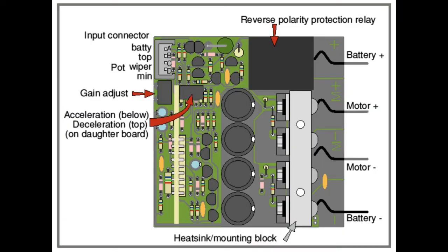We now come to the power amplifiers that drive the motors. When discussing voltage control, we assumed a smooth DC voltage. If we used an analog amplifier to provide this, it would be incredibly inefficient, particularly at high current, low speed. What is required is a pulse width modulated amplifier, or PWM. I don't intend to explain PWM, there are plenty of videos on YouTube that do that. However, I will go into some of the details of the amplifiers used.